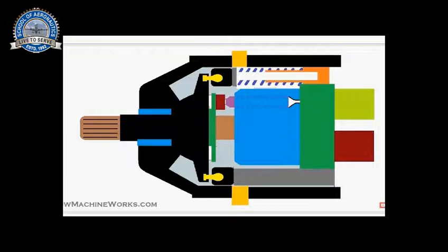So when here we have a vertical swash plate or at a 90 degree, there is no flow happening inside an axial flow variable displacement piston pump, but it becomes variable according to the swash plate angle when it increases or decreases. So how cylinder block and piston rotates, let's see that. Here you can see it's rotating over here. The cylinder block rotates, so it's a single piston that I have shown, it's rotating, but there is no reciprocating motion for the piston over there because the swash plate is vertical, so there is no flow happening. And let's see the other part of it.